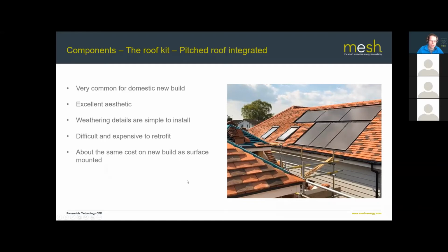On a new build, the cost is about the same as surface mounted, and that's why you'll see a lot of developers using this technology, because it gives a good return for them. Just worth noting, there is a small performance loss against surface mounted, and that's because the panels will get ever so slightly hotter than they will when they're surface mounted, because the air can't get around the back of them quite so well. That, in practical terms, in the UK, will work out at about 3%.